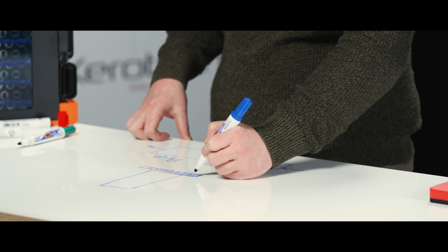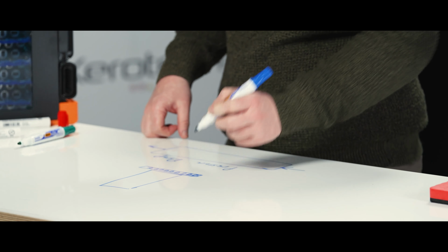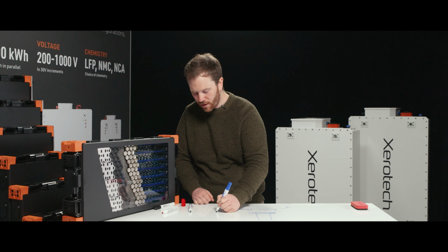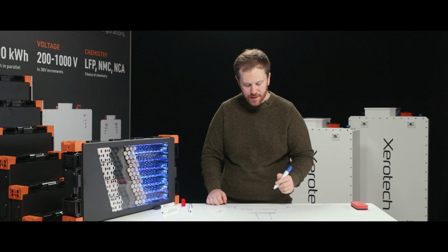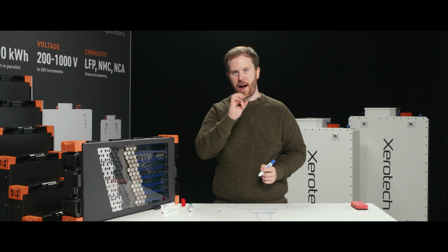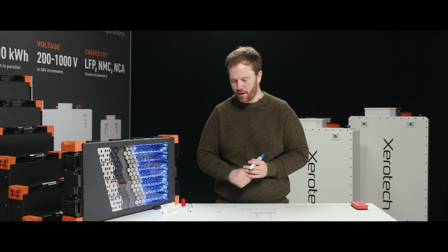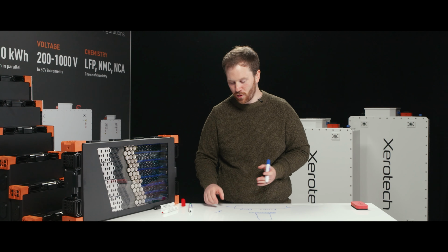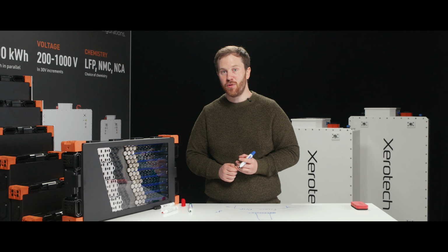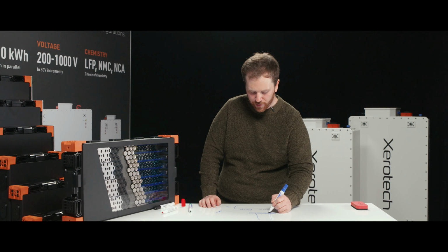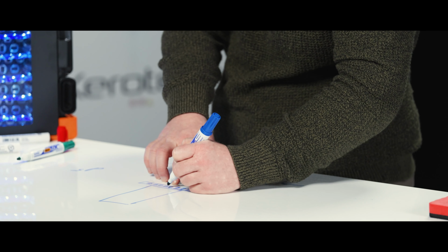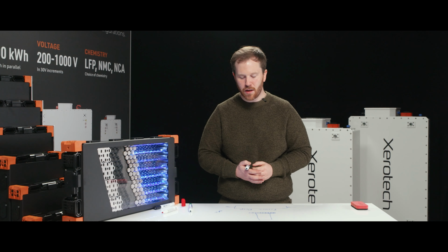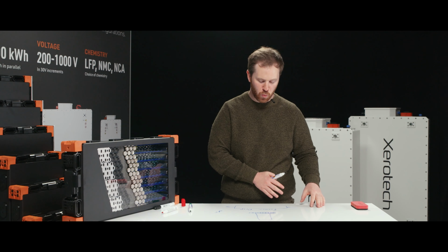But what's important is that that pressure drop equation is very non-linear. It actually goes up to the power of 5, the diameter to the power of 5. So that means that if you had a pipe and you made it half as small or half the diameter, the pressure drop overall, due to an equation called the Darcy-Weisbach equation, will go up by a factor of 32 times. So what this means is that having small openings in your cooling systems can result in huge, huge pressure drops.